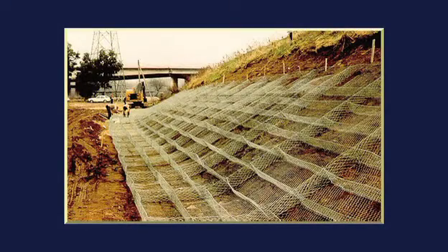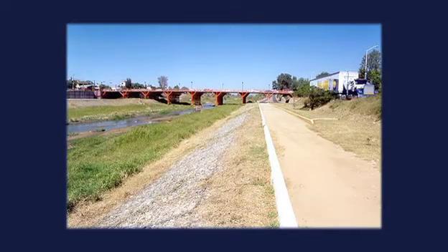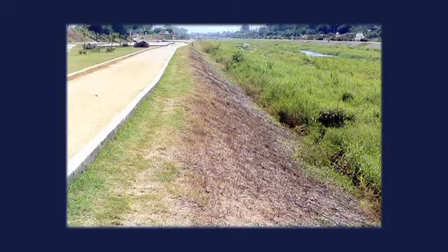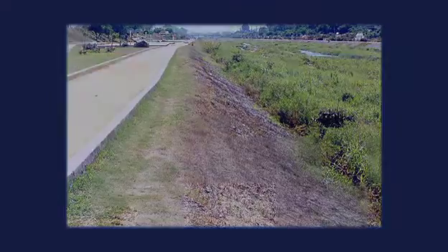Gabions are bank stabilization structures consisting of mesh baskets filled with small riprap. A gabion structure may consist of several baskets. Since the riprap is enclosed with wire mesh, gabions have a high resistance to erosion. Vegetation is able to grow within gabion structures. Planting vegetation within gabions improves habitat, decreases flow velocity, and enhances the aesthetic appeal of the channel.